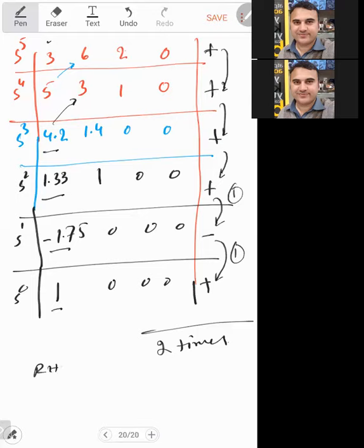So in the right half plane we have 2 poles. In the left half plane 5 minus 2 poles. The rest of the poles will be in the left half plane. And since there are poles in the right half plane, we can say that this is an unstable system. So this is the case when we got the first entry as equal to 0.